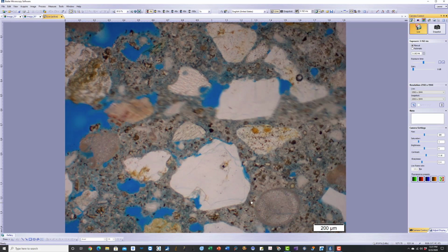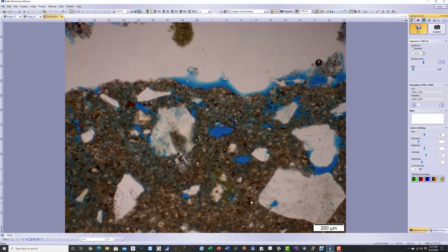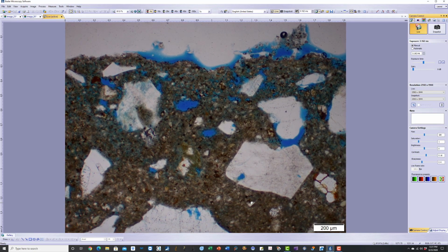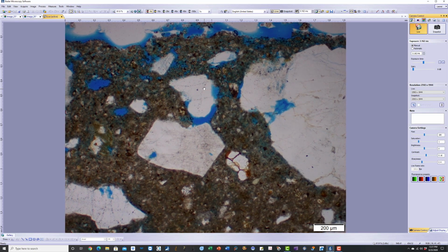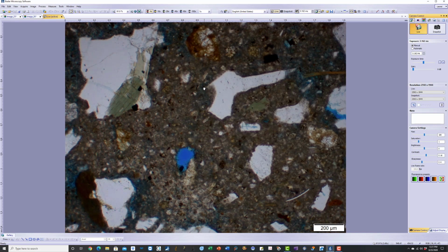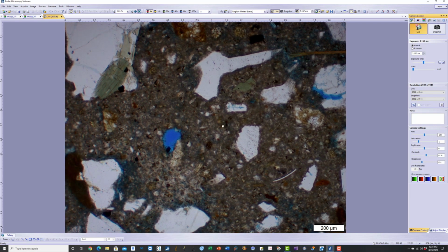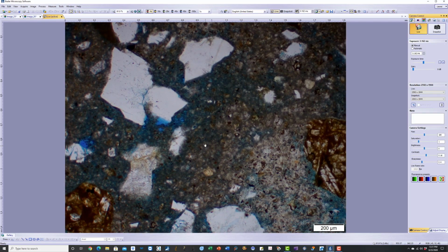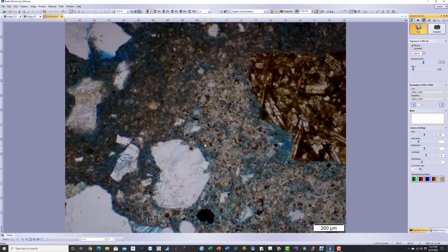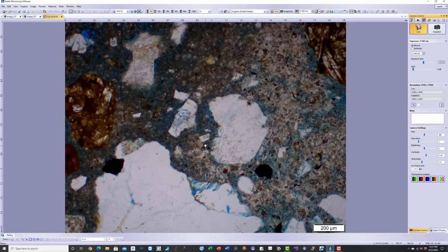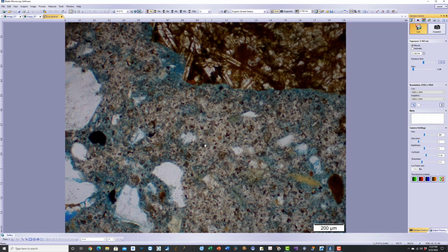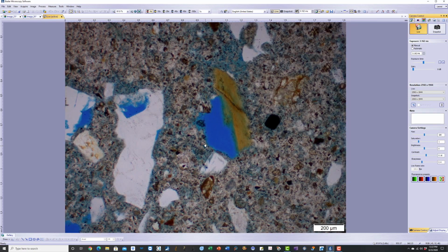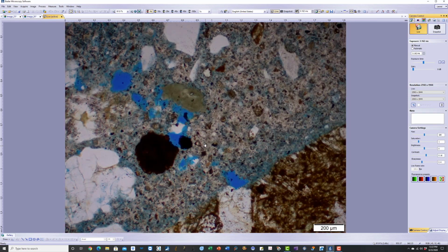So after the mortar coating, you have this densified carbonated concrete portion. After the top layer of the porous carbonated concrete, after the densified carbonated concrete comes the concrete itself. You can see it's also only Portland cement as the sole cementitious material, no fly ash or slag or silica fume. Any other pozzolanic or cementitious admixtures are not added, only Portland cement. A mixture of silica sand and the volcanic sand and the volcanic gravel and crushed gravel coarse aggregate. That's the recipe of this concrete.